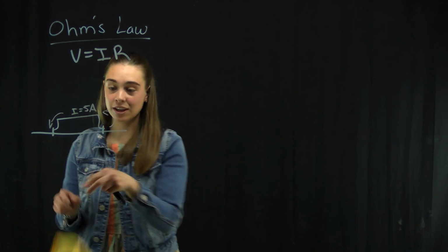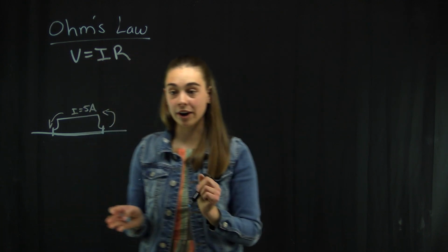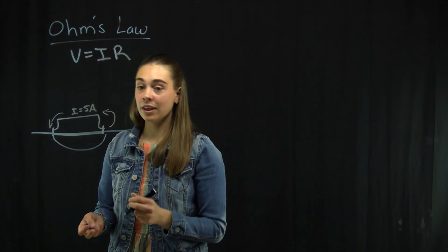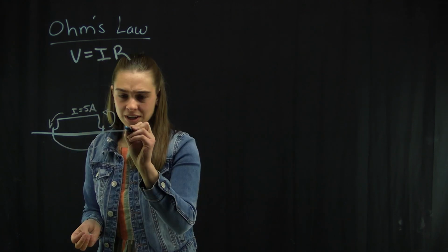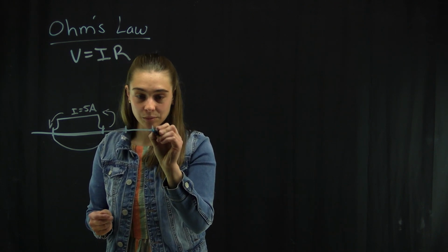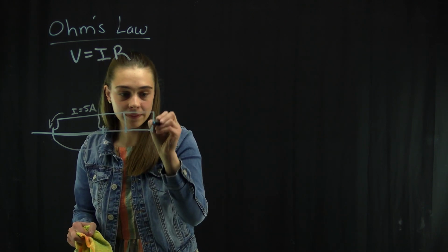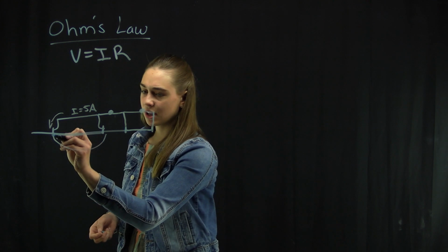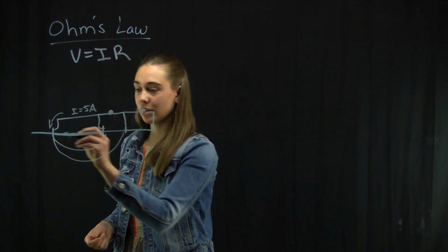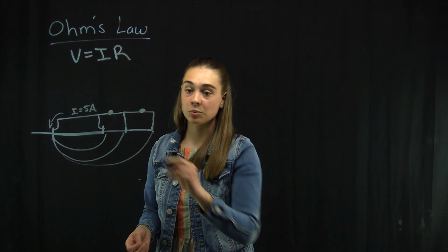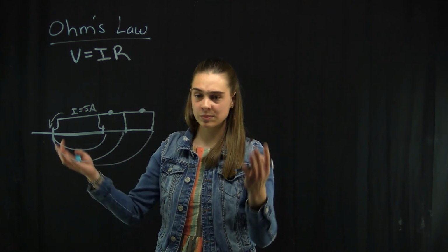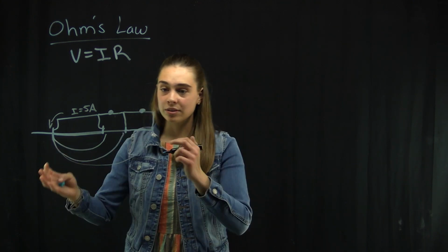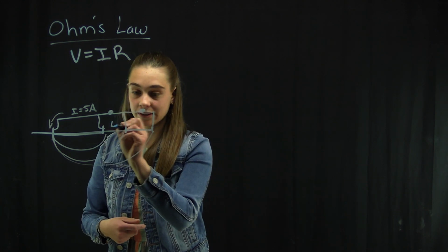But the current can basically go anywhere it wants, wherever it'll flow. So it can go either just straight across the ground, or it can have a nice little ray pattern, or it can go down and out and travel through the material in the ground. We can add more electrodes in the system. And we can say they're all connected to this system where we then have voltmeters here, and a voltmeter here. And we can have different ray patterns from the current up here go through and go to more electrodes. The more electrodes we have, the greater spacing we have, the deeper in the earth we can image. So these all have a similar length. We're going to call this length L.